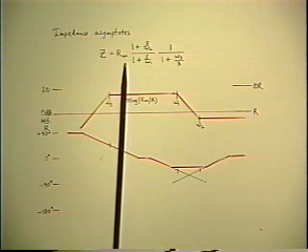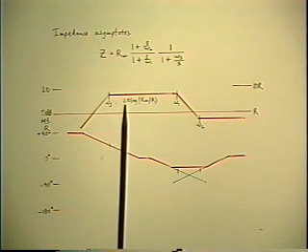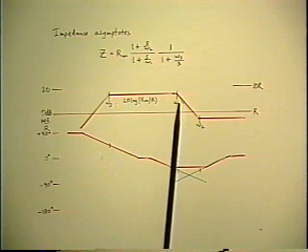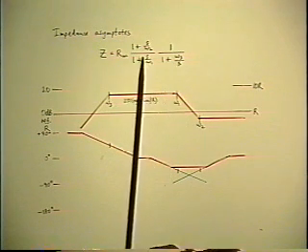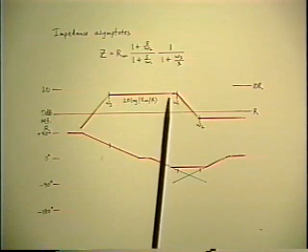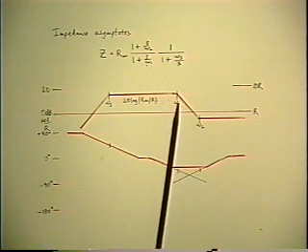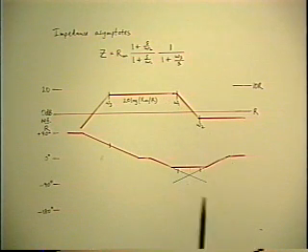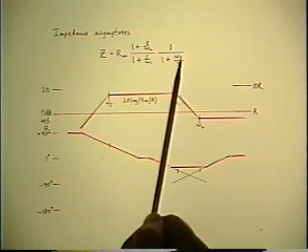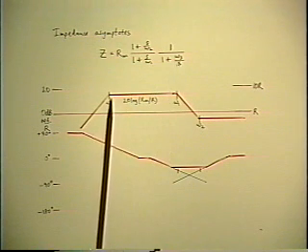So Rm now has the significance of a flat resistance. And looking up in frequency from the reference value of the resistance, we encounter a normal pole at omega 1 followed by a normal zero at omega 2. And if you look downwards, you encounter an inverted pole at omega 3.